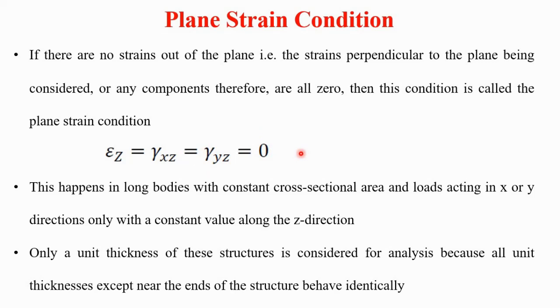So plane strain exists when loads act only in the x and y directions, and the load is constant along the z direction.